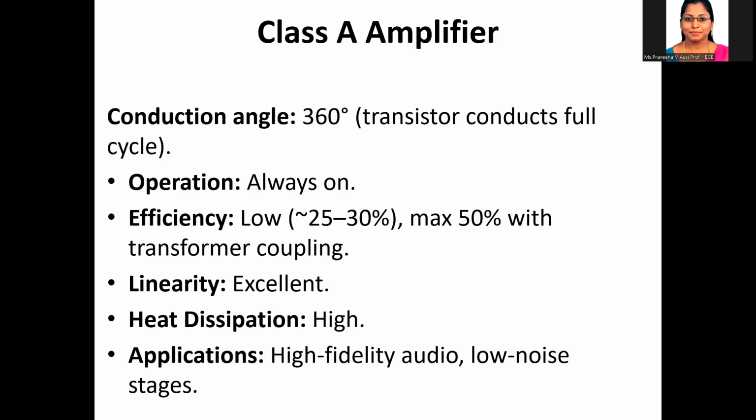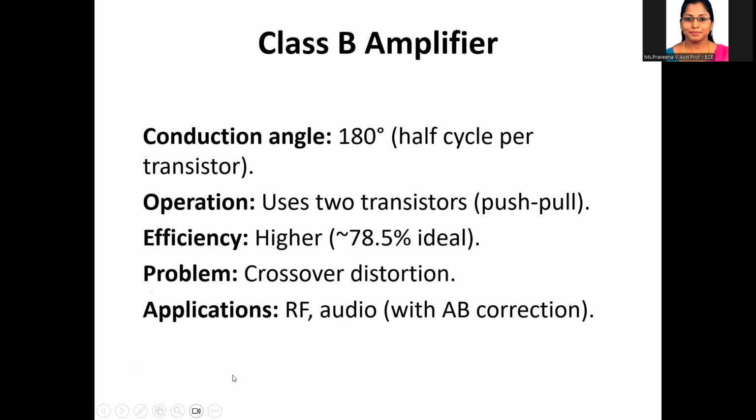It gives excellent linearity, very low distortion, high signal fidelity, and simple circuit design. But the efficiency is very low, due to the continuous current flow. Applications are high fidelity audio and low noise stages, where Class A amplifiers are used.